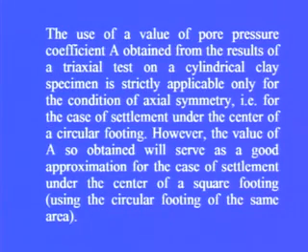The use of a value of pore pressure coefficient A obtained from the results of a triaxial test on a cylindrical clay specimen is strictly applicable only for the condition of axial symmetry, that is for the case of settlement under the center of a circular footing. However, the value of A so obtained will serve as a good approximation for the case of settlement under the center of a square footing using the circular footing of the same area.